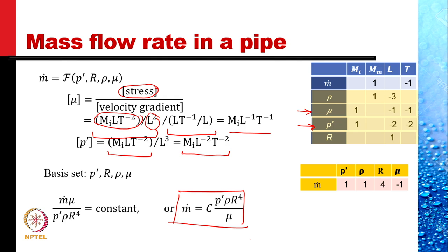So it should be apparent now that we increased the dimensional set to have one more member, and that we did by splitting mass in its dual role as inertial and as quantity of matter. So the value of R increased to 4, N was 5, so there's only one non-dimensional group of parameters, 1 pi, that was needed.